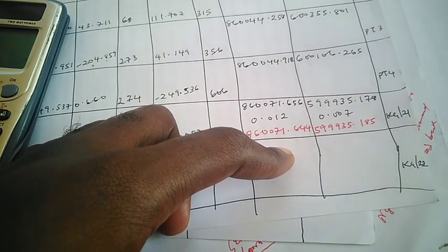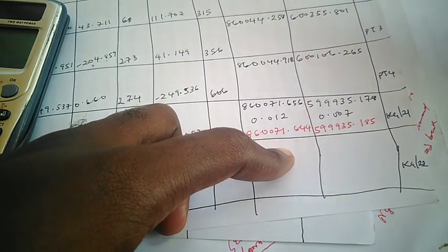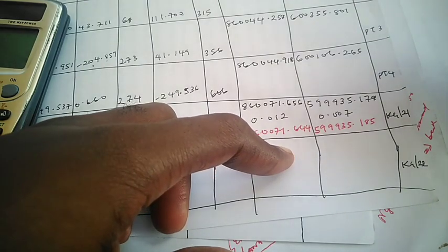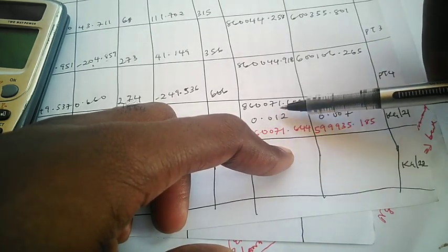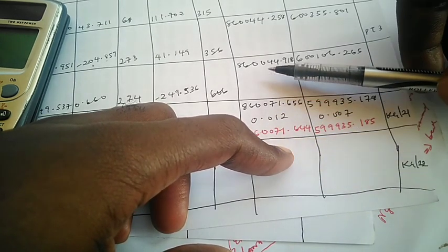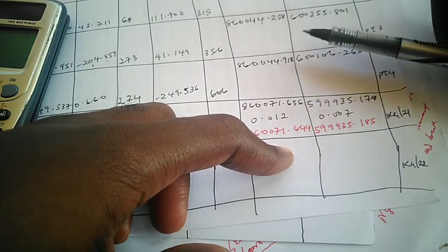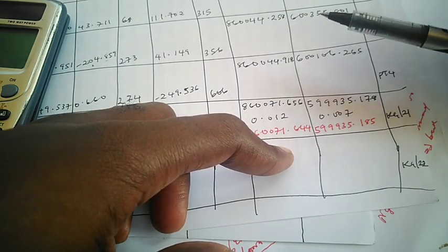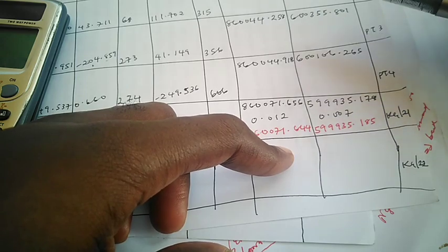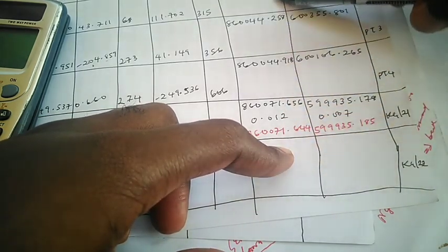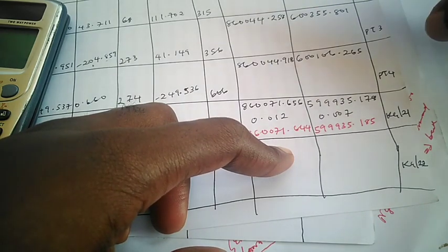I know many people will say just go straight to the point. But the reason I take time to explain this in depth is that immediately you make a mistake on the sign and start distributing the correction with a wrong sign, the coordinates you get subsequently will also be in error. Therefore, you need to understand what the sign is from this point, so that by the time you distribute it, you will use the appropriate sign.